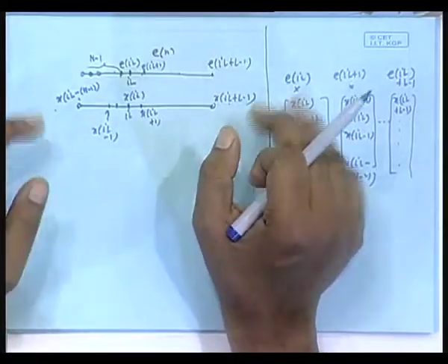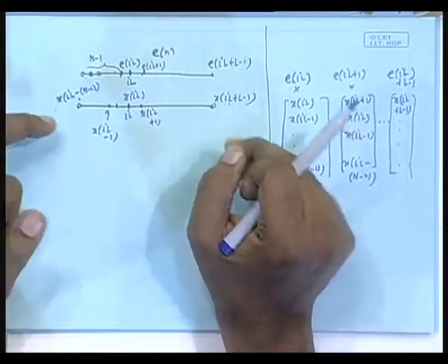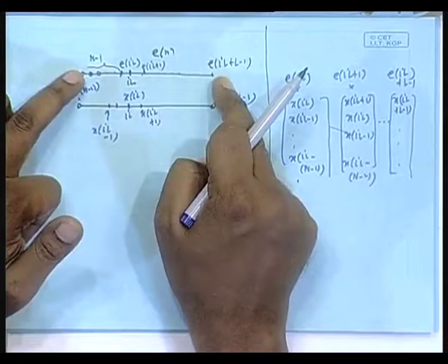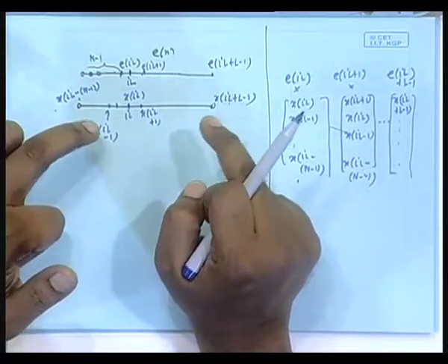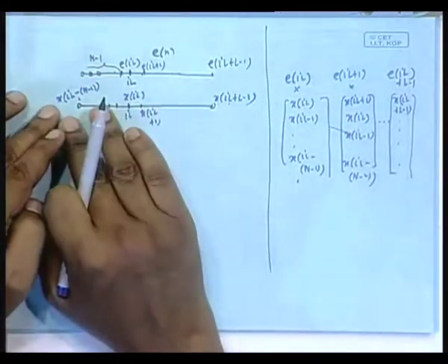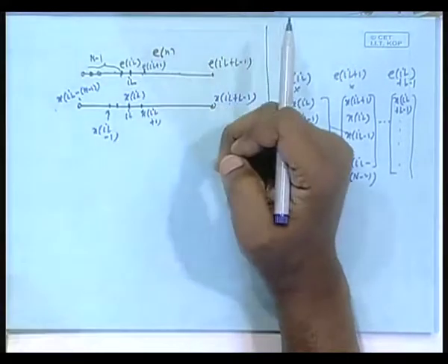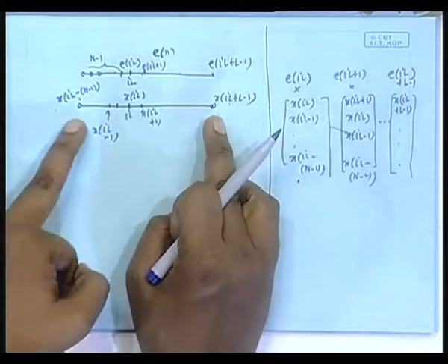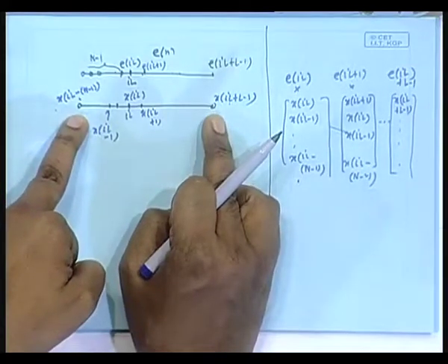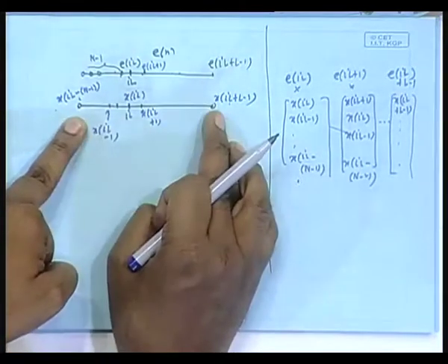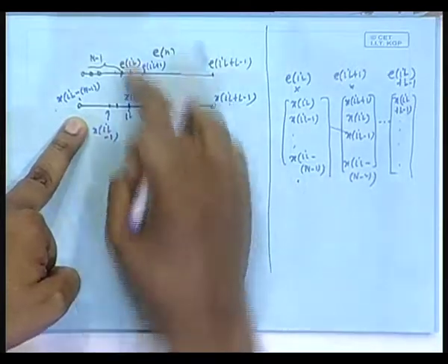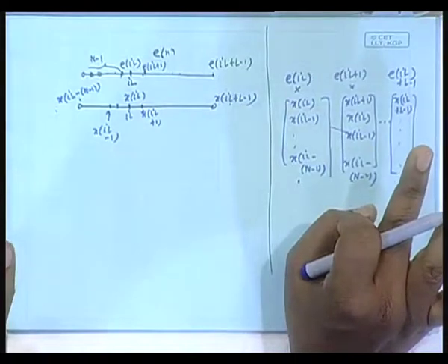So, you remember that this is something we do in circular convolution. What do we do in circular convolution? One sequence I hold as it is, the other sequence I make a periodic version, reverse, I shift, and chop off the right and left, and do sample wise multiplication. So, with 0 shift, this is a 0 shift case, but after reversal, that is why if you multiply sample wise you get the first entry of the vector, isn't it?